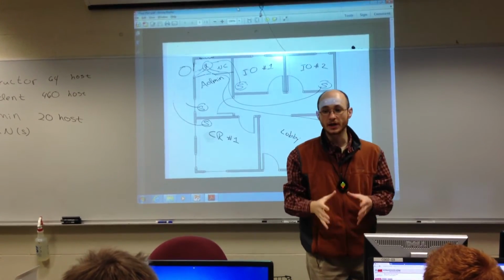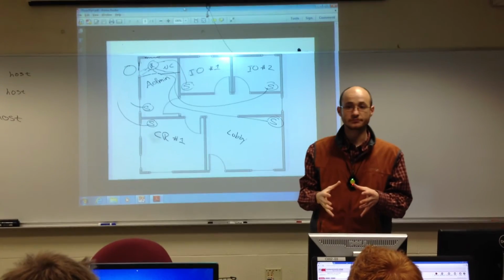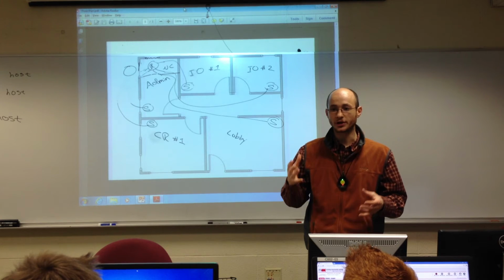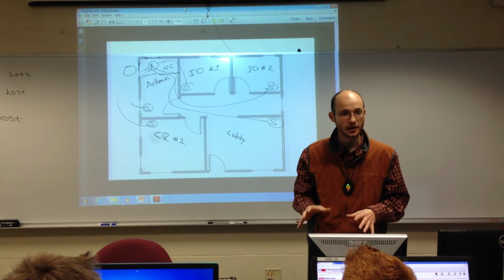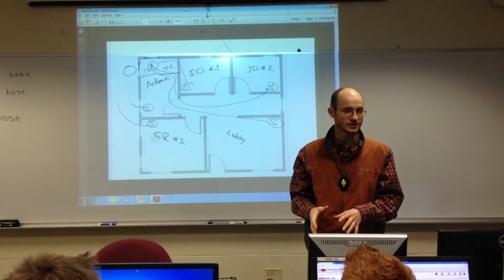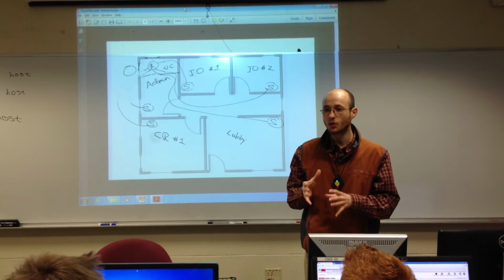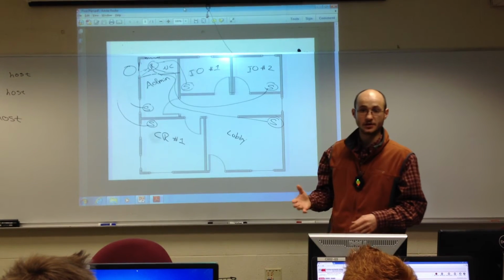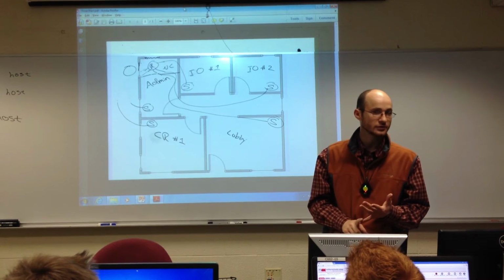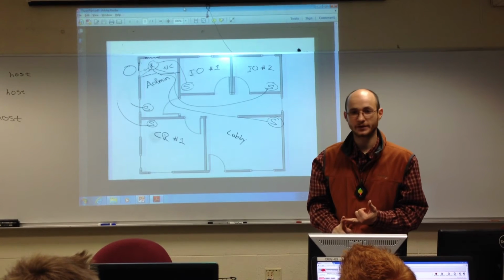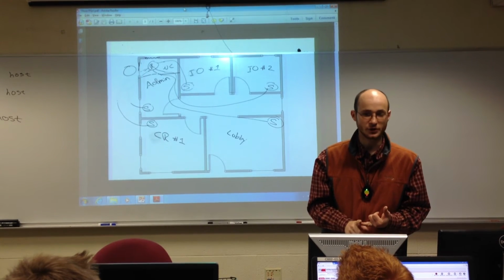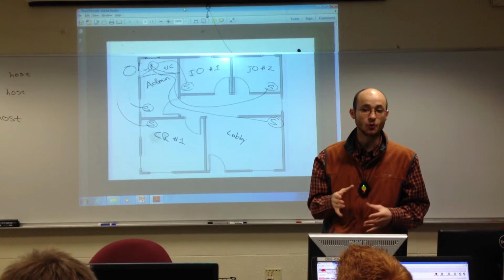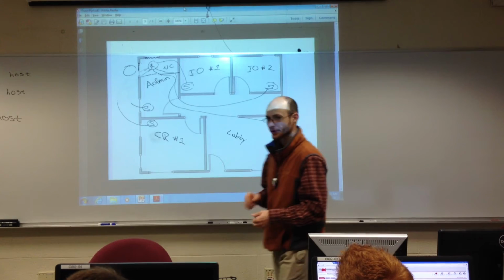And I strongly recommend that you get a conduit pipe, 6-inch pipe, and you install that. Put it in the wall, put it on the outside of the wall. I don't care because this is your wiring closet. People don't get to see the wiring closet. The reason why you're going to run this pipe up and down the building is that if you ever have to add a new network, or divide a room in half, it's going to be so much easier for you to add wires in the future by having that conduit. And by the way, when you run that pipe in there, put a piece of string in there.